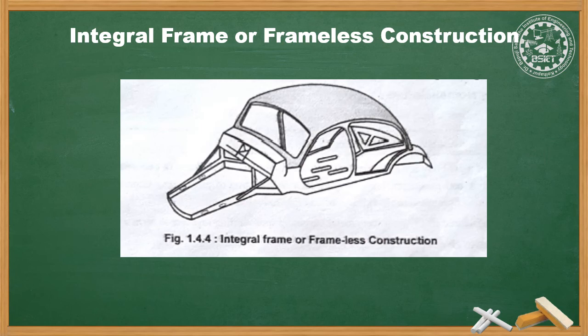That is, the side members are eliminated and all mechanical components are attached directly to the body. These bodies are made up from pillars, rails, seals and panels, all welded together, and a reinforcing channel section under the frame with an extended subframe at the front is provided to replace the chassis. In case the body shell and underbody are welded together into a single unit, the underbody is made up of floor plates.